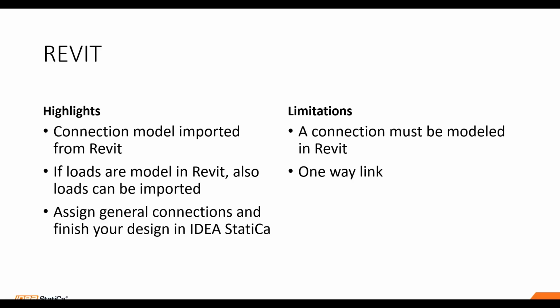Okay, so here are the highlights and limitations. The connection model is imported from Revit. If loads are modeled in Revit, loads can also be imported, so it's up to the user if they want to add the loads there in Revit and transfer that to IDEA StatiCa, or just type the loads in IDEA StatiCa directly.